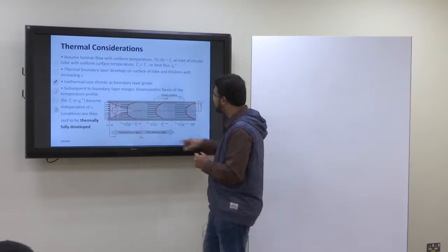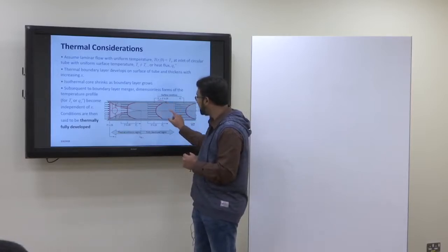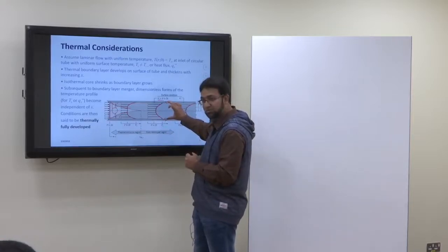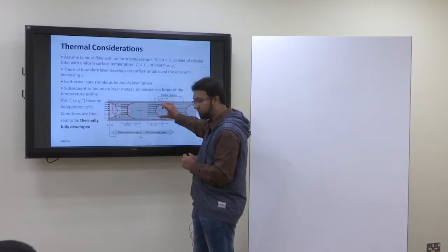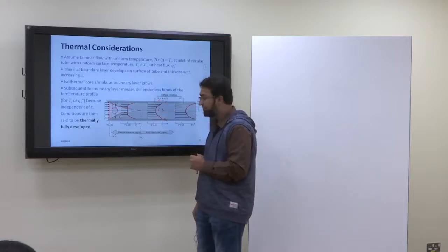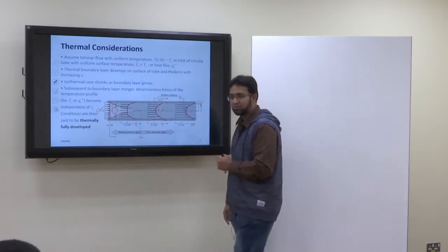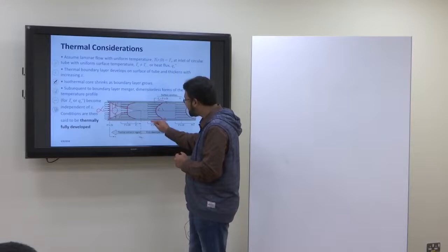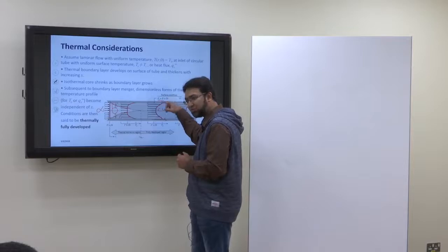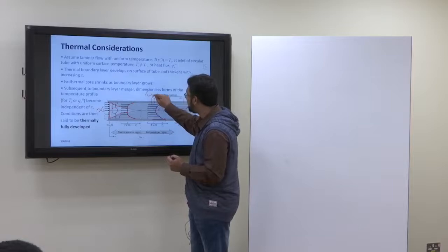Okay. So suppose the surface temperature is high. The top will be the surface temperature and the bottom will again be the surface temperature, and these will be the high temperatures. But the temperatures will fall until they reach the centerline temperature, and you have a T infinity temperature here. If you want to know the temperature at a specific cross section, you will not consider this variation, you will take the mean of it. So you will have a mean temperature here, T mean.